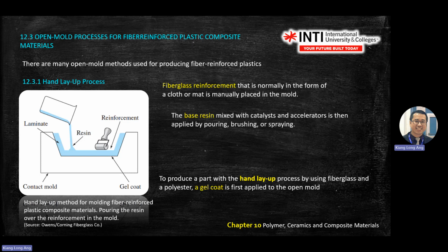It's very, very small, like a needle. If you're not careful, you suck in the fiber and it will stay in your lung. It's like a small microplastic. So when you handle composite processes, please wear a mask with a filter, not the normal patient COVID kind of mask.